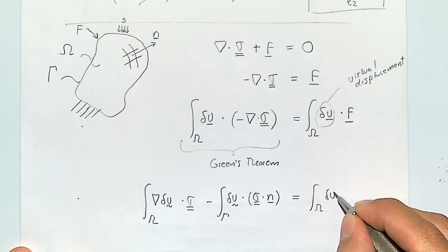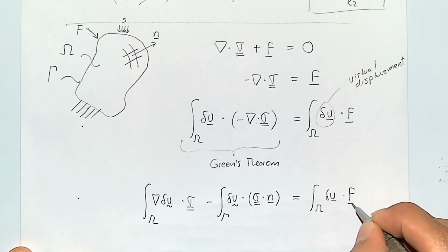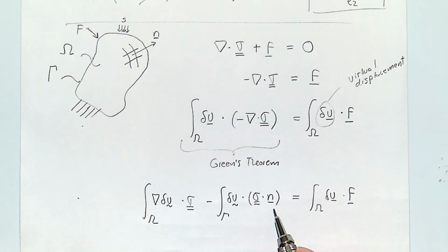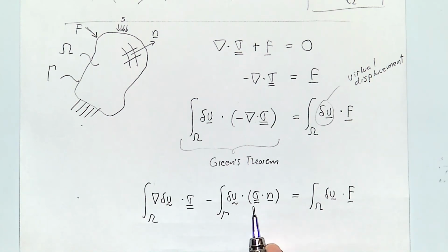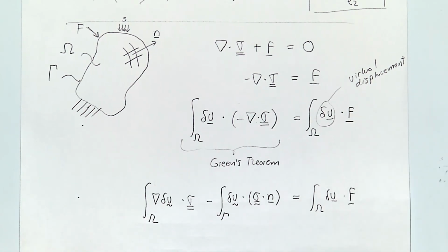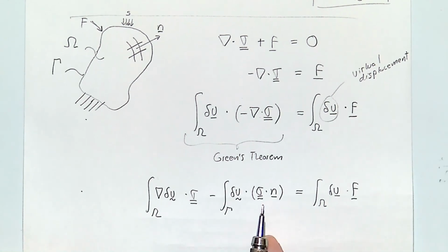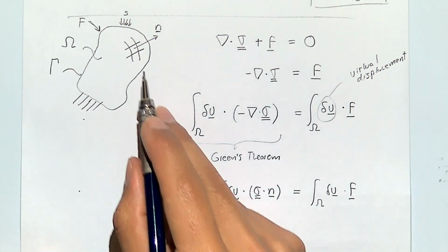Anyone remembers that? You did that for project number 2, number 3. Stress projection on a plane, right? Yes, it's a stress projection on a plane. This is actually what is called a traction vector, but it's the stress on a plane. This is the direction of the plane. This is the stress. You multiply those two, and that's the result of the traction vector on a particular direction. And notice that that traction vector now is applied over the surface of this volume.